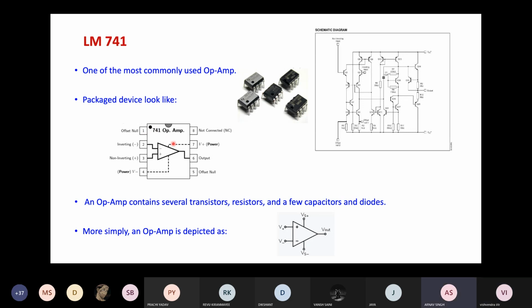Okay. So what is the function of pin 8? It's not connected. It's there just to keep a symmetry actually. So it's not needed at all. Okay, so it is just a pin. It is not connected to the circuit inside it. Only 7 pins are connected. But in order to make a symmetric integrated circuit, we need to have 4 pins on both sides. We cannot have 4 pins on one side and 3 on the other side. That is not a good structure for handling.